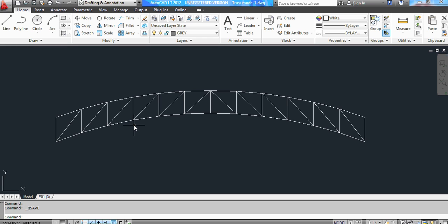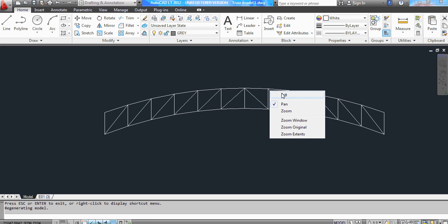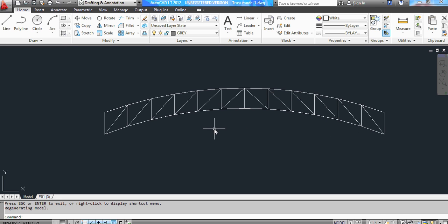Also, the software reads lines as your truss elements, so make sure the only lines in the AutoCAD environment are the truss. It might be better to even zoom in and make sure nothing else is seen.